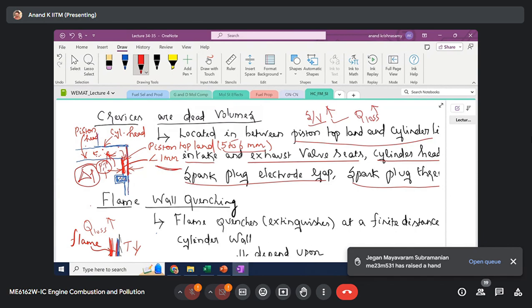Please note that the mixture is ignitable, because we generally prepare an ignitable mixture. But the problem is that we don't have a flame during that period to ignite it. Since the pressure and temperature are considerably low and there is no flame, only slow oxidation or partial oxidation of these hydrocarbons can take place, and thus it becomes a source for HC. Since it is only partially oxidized, during the exhaust stroke, along with the exhaust gas, this hydrocarbon goes through the tailpipe and is discharged into the atmosphere as an unburnt emission.